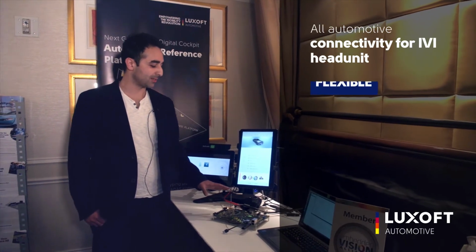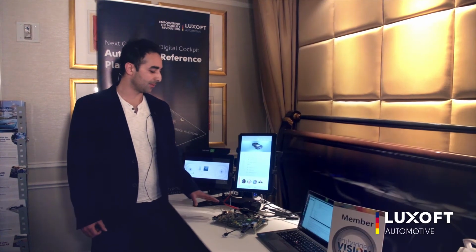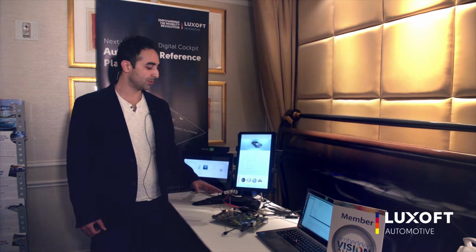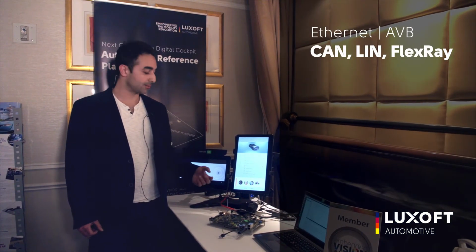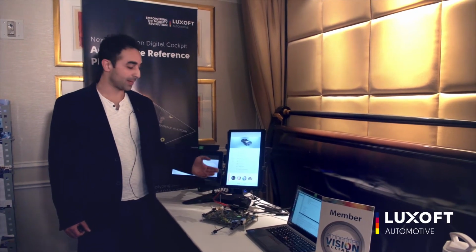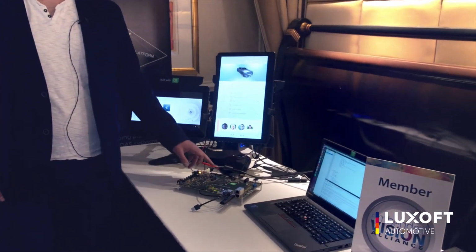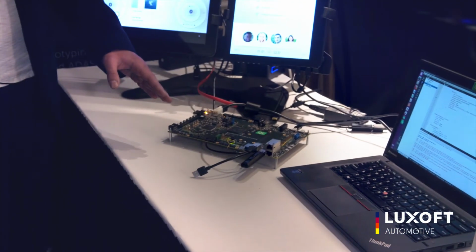This board is intended to be as flexible as possible. Other than all the connectivity we have on the board, which is what you would typically want in an IVI system, like CAN, FlexRay, LIN, Ethernet AVB, Dirana tuner from NXP, digital radio, we also have two expansion connectors, which you can use to connect various interfaces to the board.